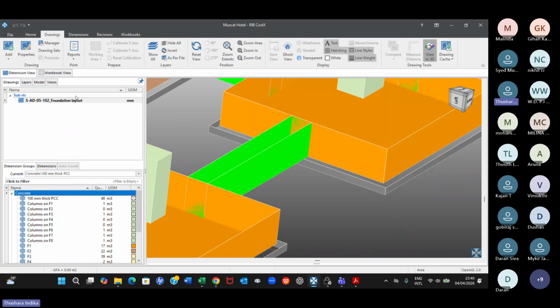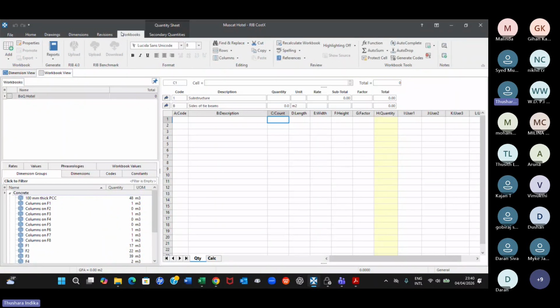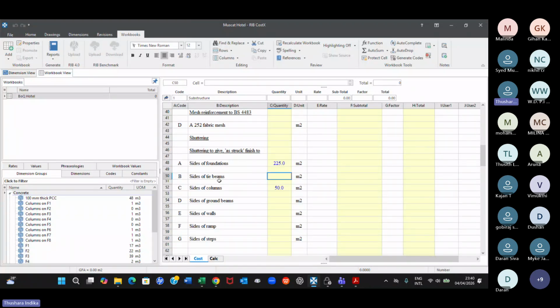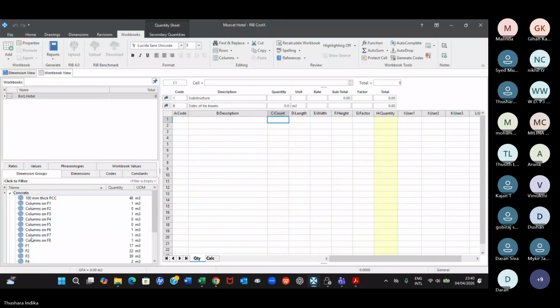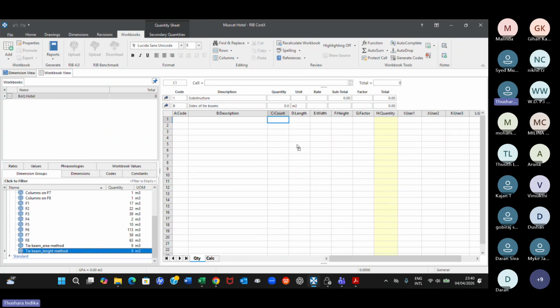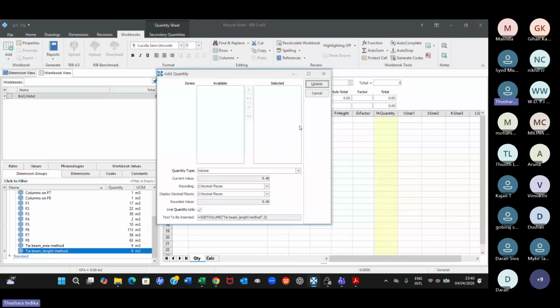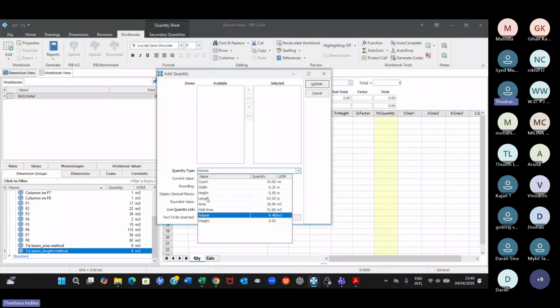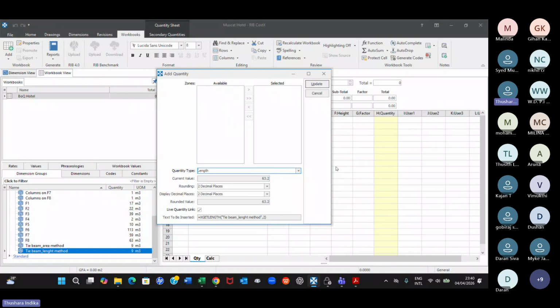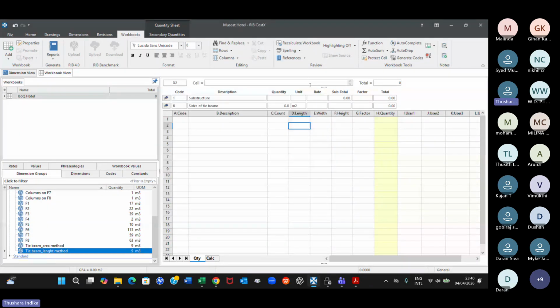So we are going to do that now. So I mean here, sides of beam, with this will stop. Okay. And you get the length. That's why I measured this and drop it here. And what you need is not the quantity. What you need is basically the length. 63.2 meters of tie beams. Not both sides. Not both sides. It is only one side. It's the total length of tie beam. Put that way. Total length of tie beam, one side. So you have 2 times 2. And height is 0.5.